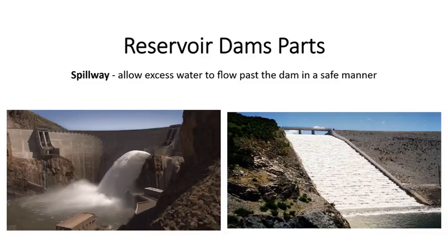And what the spillway does is it typically has a rough surface, like the steps, as you can see in the figure on your right. It has steps which induce turbulence on the water. And the turbulence, as you can see on the animated GIF on your left, actually dissipates energy of the water that is being spilled out from the dam.